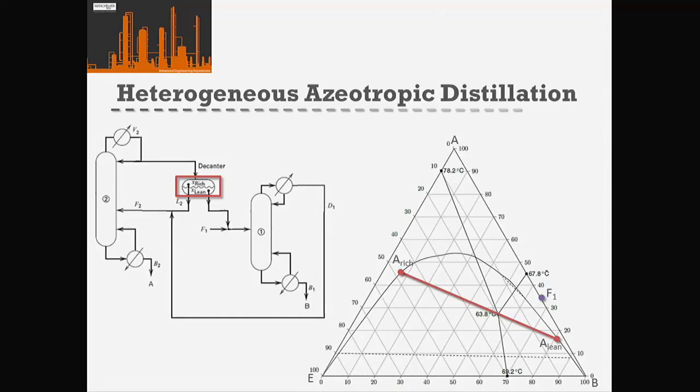So what's the advantage of actually making this product here the ternary azeotrope composition. Okay, so the reason that we do that is it's actually the only point on the diagram that's accessible from every region. Yeah? So this azeotrope here, we could come to it from this region, we could come to it from this region, or we could come to it from this region. Yeah? So it gives us that flexibility to design to this point from anywhere on our ternary diagram. Okay?